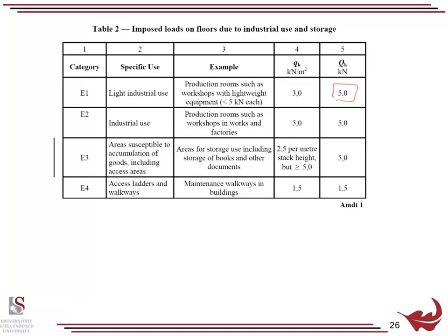They would store big, heavy material. And so that was an agreement between us and the management, and they were happy with it. At least then, if their staff did something silly, it was safe. Whereas on other floors, we might get to a 20 kPa floor load. I mean, we had floors where they would store big piles of material, and there you could have 2 tons a square meter of material being stored that you would need to design for.